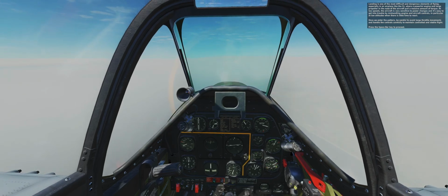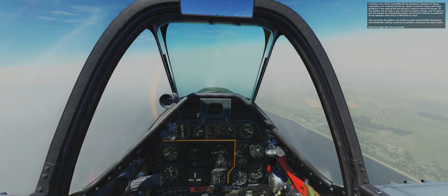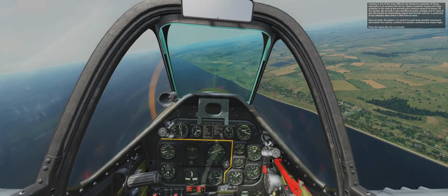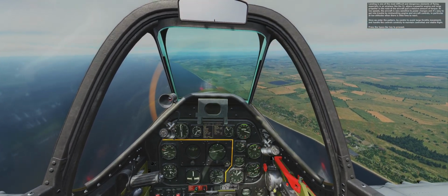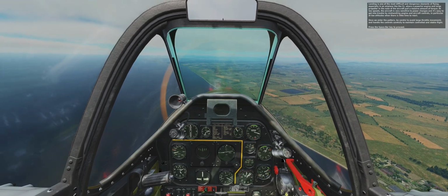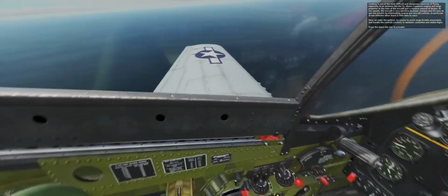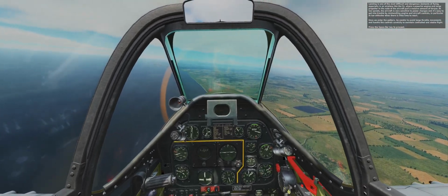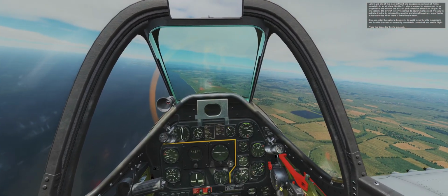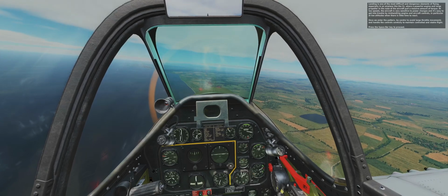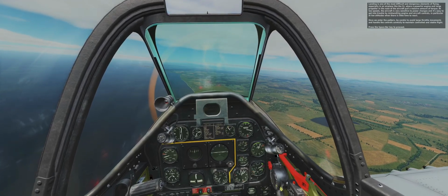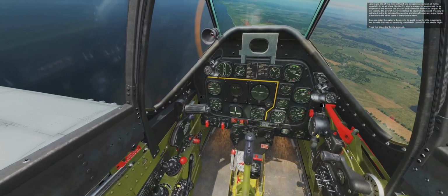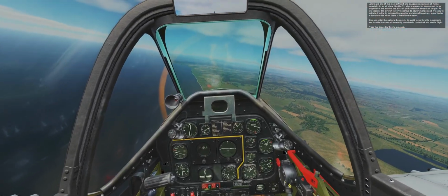Landing is one of the most difficult and dangerous elements of flying, especially in an airplane like the P-51, where a powerful engine and large propeller in the nose of the aircraft pull a massive amount of torque. At low speeds, the aircraft is very sensitive to power changes, and it's easy to get into trouble by mishandling engine and aircraft controls, in particular at low altitudes when there's little time to react. Once we enter the pattern, be careful to avoid large throttle movements and handle the controls carefully to maintain controlled and stable flight. Press the space bar key to proceed.